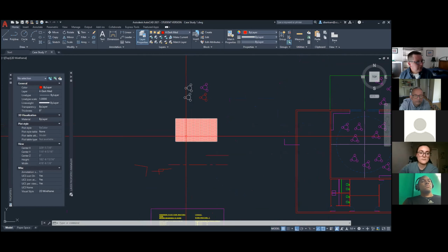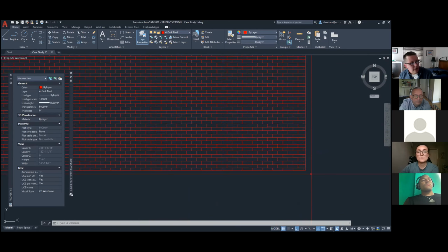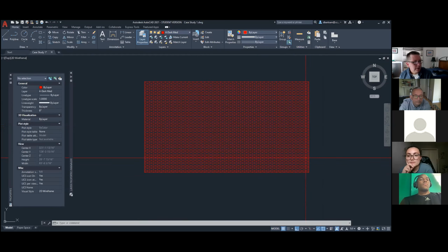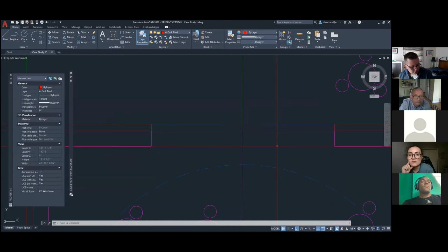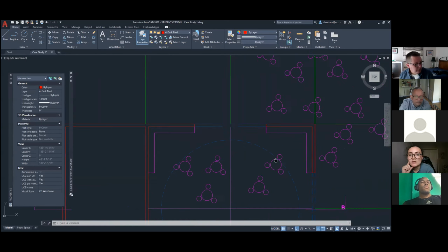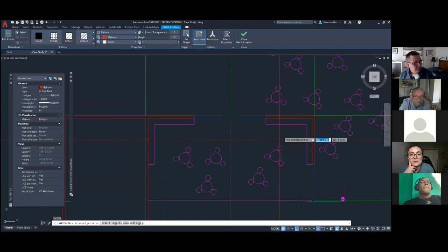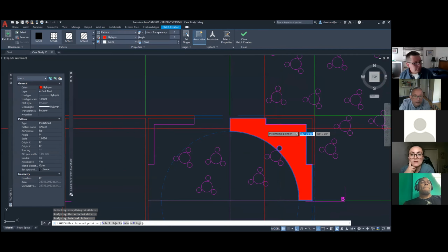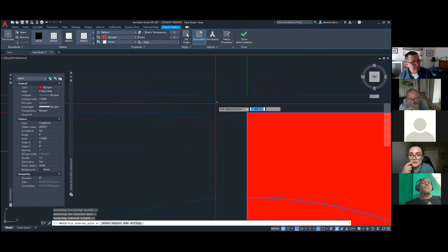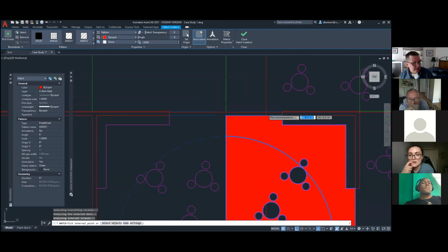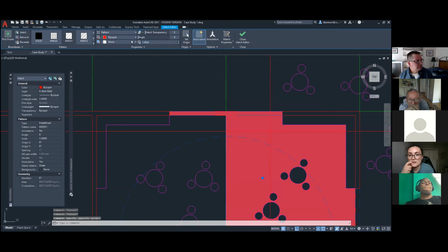Okay. One thing I meant to talk about and we didn't: when I was talking about hatches, it's important to know, and not that what you're describing is a problem, that just happens. So what Romina is explaining, let me just show you quickly. So hatch. That belongs there, this all gets filled in. And what I was saying to a few of you, right here, that's the threshold, and it appears empty to me. I think you missed your hatch in the threshold. So let's just select this and get it looking the way it should, roughly.